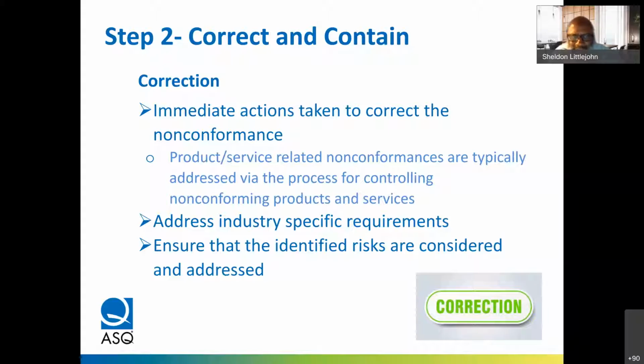The gauges go out and we realize that the gauge was out of the acceptance criteria, and we need to make a call on how this may affect product that was shipped to our customers, or product that may have been accepted as being within the tolerance, within the limits. But if you're not able to trace this gauge back to the products, you lose the ability to determine the impact.